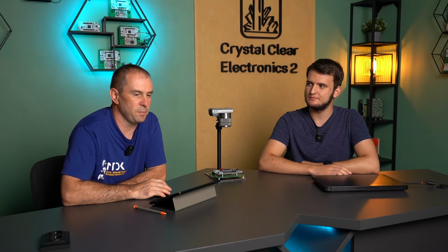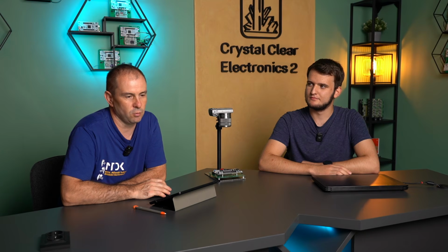Most microcontrollers have dedicated modules for the commonly used synchronous serial communications, such as SPI or I2C. Indeed, the SPI, or Serial Peripheral Interface Communication, is most commonly used within embedded systems between devices located within a short distance of each other, mostly using a master-slave structure. It is a subordinate connection where devices can have two roles, master and slave.